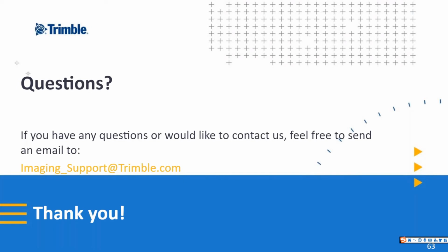Question: any idea where SmartBase download is available? So there is a service that Applanix is connected to. So your POSPac is connected to the default service that downloads available base stations. And this is just simply the button that is called Find Base Station in POSPac. If you would click the button as was shown in the presentation, you'll get a list of all the available base stations that you could download. You could also, of course, add your own base station as was explained before, and you can also add your own base stations database. So POSPac could look into that and download base stations.